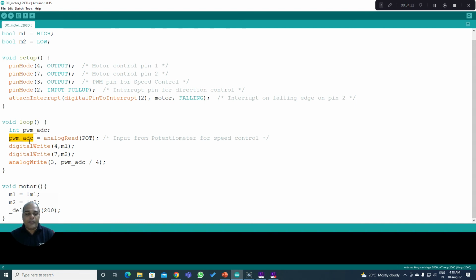So in order for PWM to get activated, we need to convert this PWM from 0 to 1023 to 0 to 255. It's an 8-bit scale. It's an 8-bit PWM we are going to convert. So 8-bit PWM in the sense, my duty cycle can be any of the 256 variations of my duty cycle. So 2 power 8 is nothing but 256. I can have 256 different on times possible. So our scale from 0 to 1023 should be converted to 0 to 255.